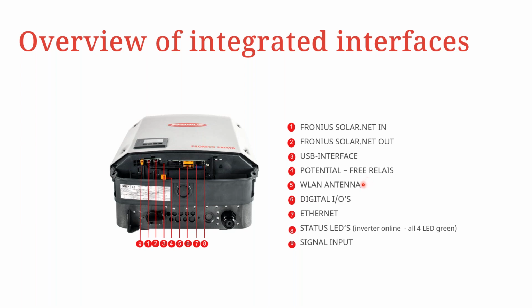The connection point for both the data manager and the sensor card, as we will see later, if they are both integrated into the Fronius Snap inverter, can be accessed through the DATCOM area, or where you do the communication cabling. So as an example here, we can see the data manager with the various ports as described here. If we had also the sensor card integrated into this inverter, then there would be a slot just below the data manager where the terminals or the connection area of the sensor card would also be shown.